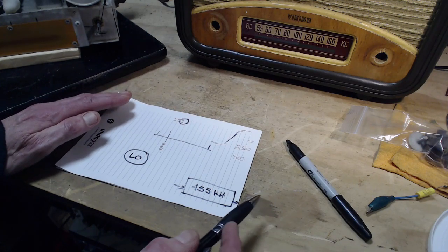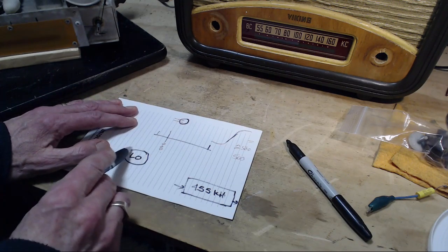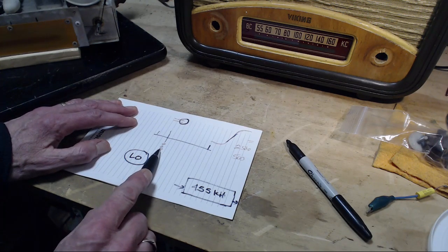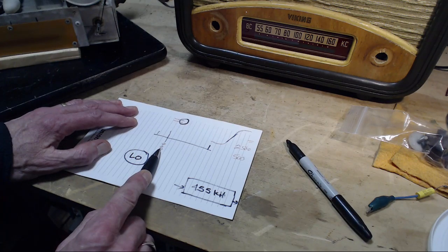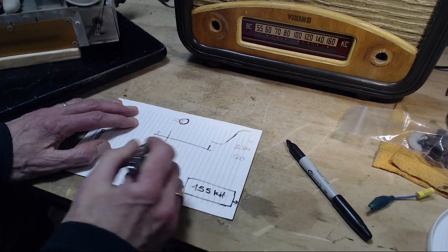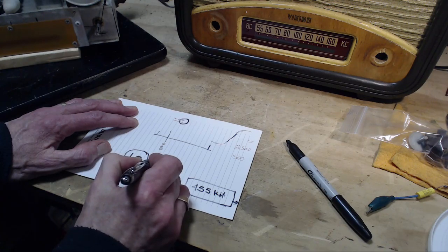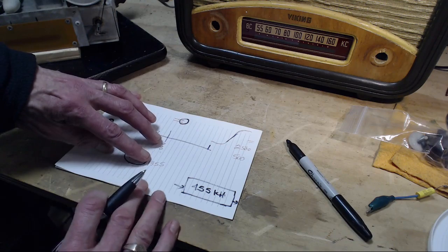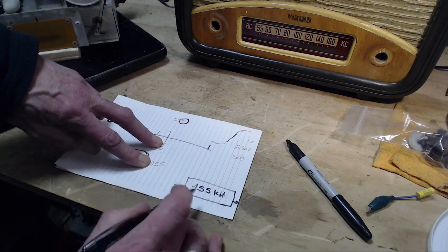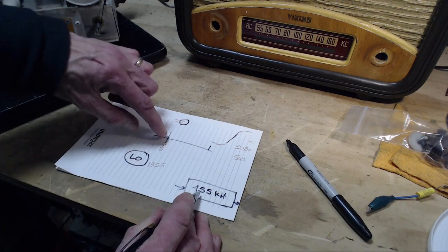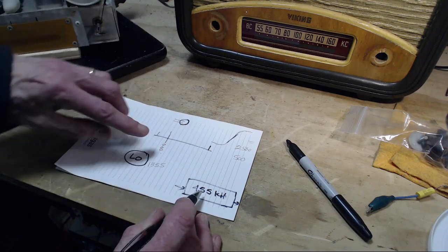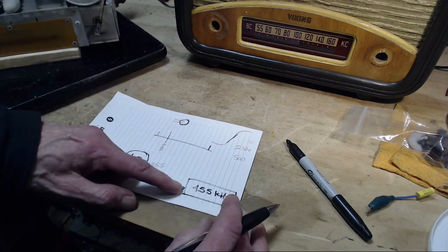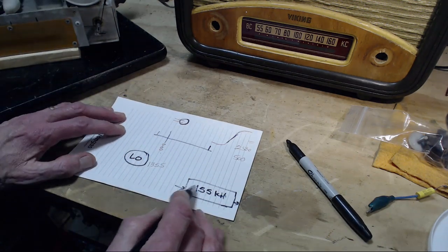So it becomes kind of simple now. We just need this signal, the local oscillator signal, to be this distance away from that. So looks to me like if we can make the local oscillator run at 1355, the difference between these two signals would be 455. And this new version of the 900 kilocycle signal would start heading through the IF and heading for the speaker.